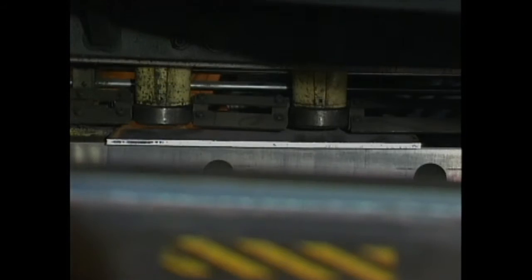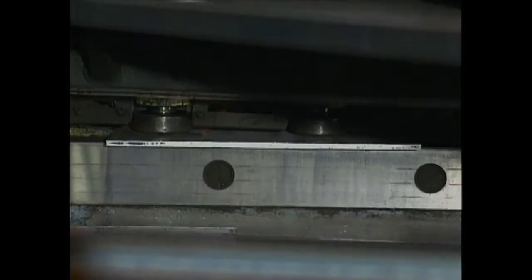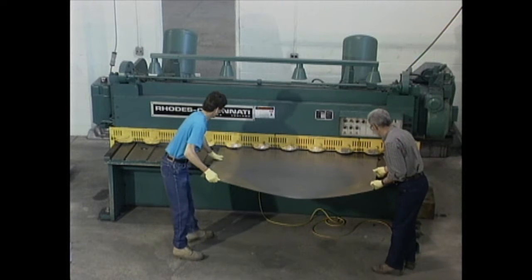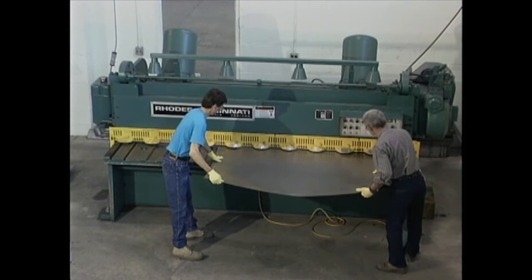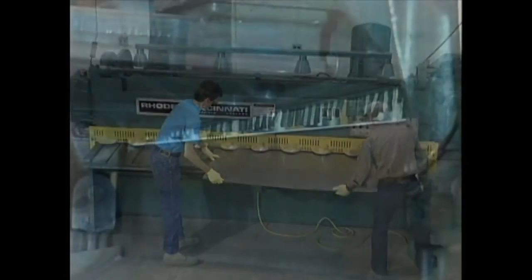of sheet metal shearing and bending. Shearing is the mechanical cutting of sheet metal by means of two opposing blades. It is used to precisely cut large sheets of plate and sheet stock into smaller, more manageable sections, which are then used in later operations.